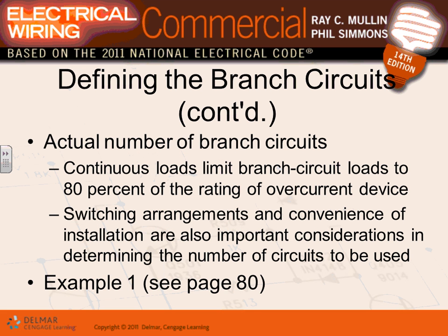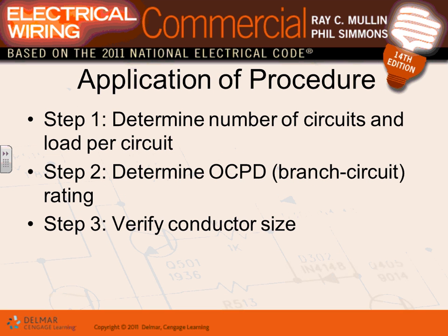Is it a good design idea? No. It's a good idea to group all the perimeter lights, put them in one branch circuit or multiple branch circuits, depending on how many of them. So that's where that goes.